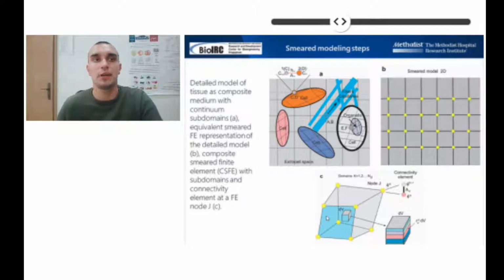One approach in modeling problems within complex composite media is to divide the entire domain into subdomains occupied by one constituent with the corresponding laws and properties and formulate the subdomain models. Then the next step is to model the interaction at the domain common boundaries and generate the model for the entire system and solve for the unknown describing the problem.